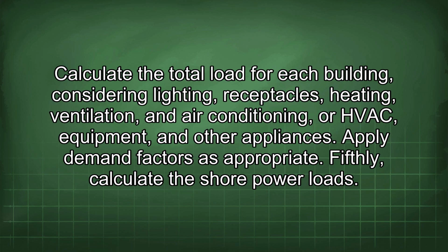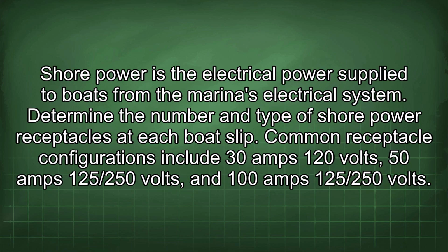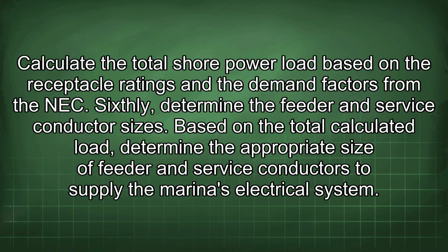Fifthly, calculate the shore power loads. Shore power is the electrical power supply to boats from the marina's electrical system. Determine the number and type of shore power receptacles at each boat slip. Common receptacle configurations include 30 amps 120 volts, 50 amps 125/250 volts, and 100 amps 125/250 volts. Calculate the total shore power load based on the receptacle ratings and the demand factors from the NEC.